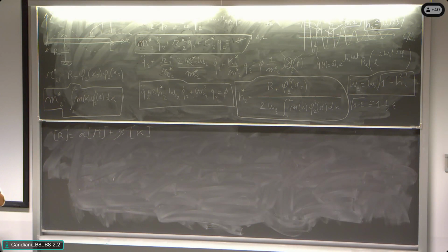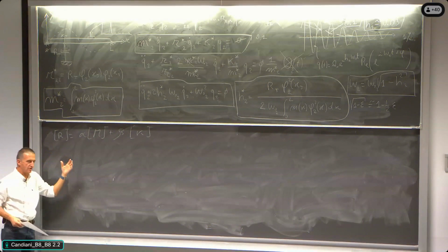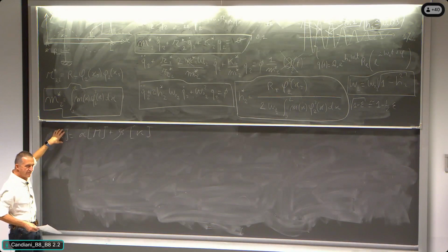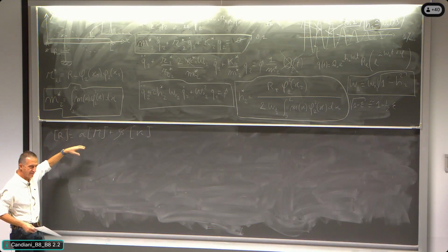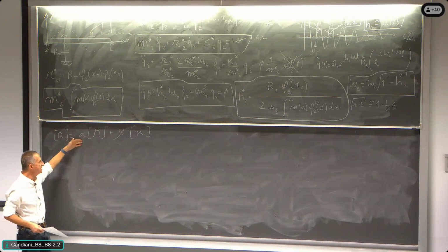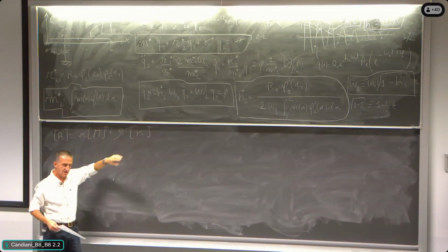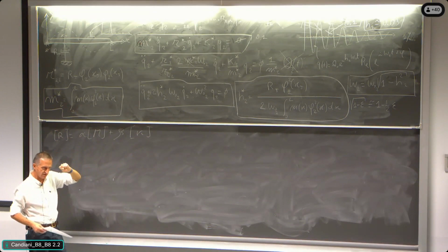And we already learned in the n degree of freedom system that in order to give a practical representation of the effect of a distributed damping, we can represent the damping matrix associated to an n by n degree of freedom system as a linear combination of the mass matrix and the stiffness matrix. So we learned this sentence.